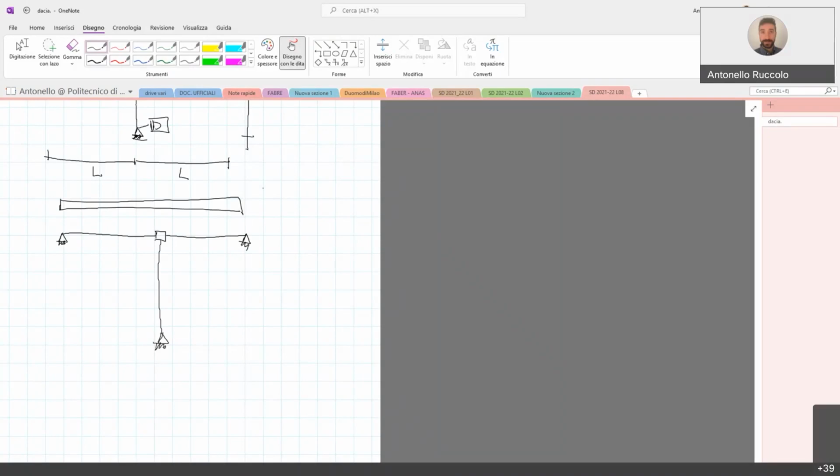No, because we are assuming that the beam A and the beam B are rigid, are axially rigid. Okay, so we say that the axial rigidity, the axial stiffness, goes to infinity for beam A and B. So since the displacement in at least one node in the beams A and B, in this case both node A and node C, we have hinges, we know that we cannot have any lateral displacement.